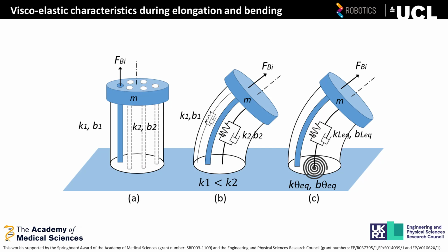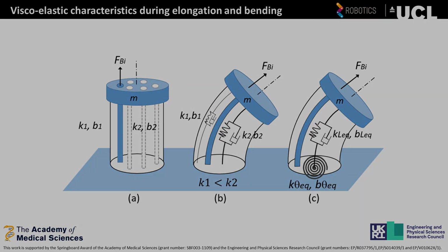These two sets of longitudinal spring dampers could be simplified with a set of longitudinal spring damper and planar bending spring damper. By similar reasoning, if we apply three different forces and produce spatial movement, a spatial bending spring and a spatial bending damper can be added to the model. Here, we have identified longitudinal and planar bending stiffness and damping ratio associated with this specific class of soft fluidic elastomer robot, and later on we have used them in the dynamic model.